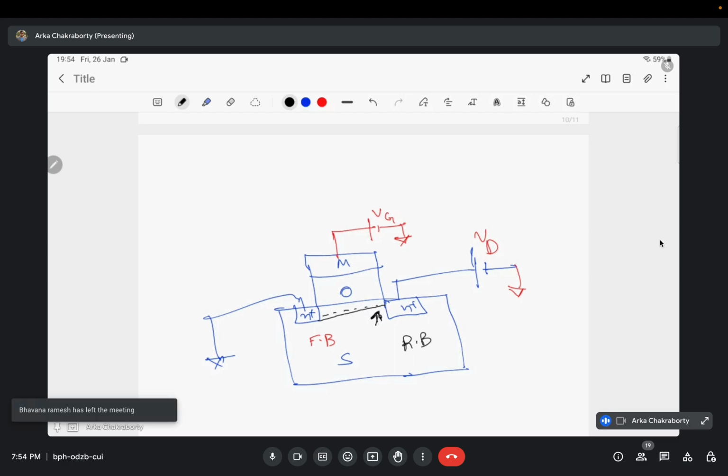That's why sometimes halo dopants are used, because of some effects. It is called DIBL effect, drain induced barrier lowering. To remove them, some doping is done in front of the drain. They are done both in front of drain and source because MOSFET is a symmetric device. I can use any terminal as drain, but this is the reason I have to make some dopings here if I want to control the short channel effects. And this is the region which, as it is reverse biased, is trying to sweep the electrons from here.